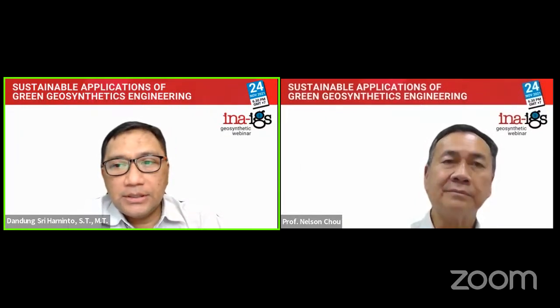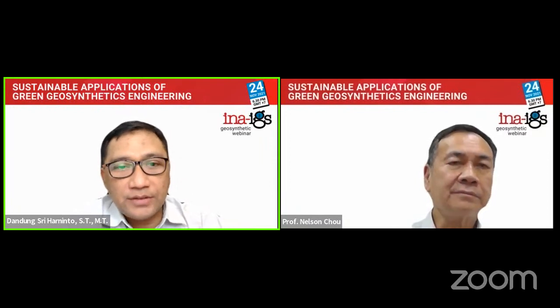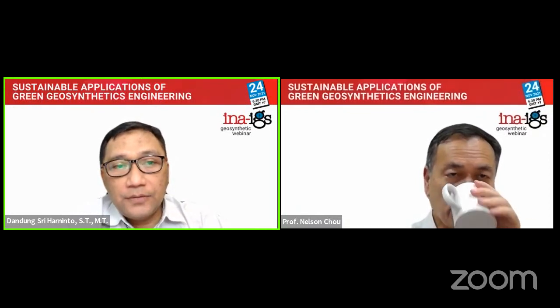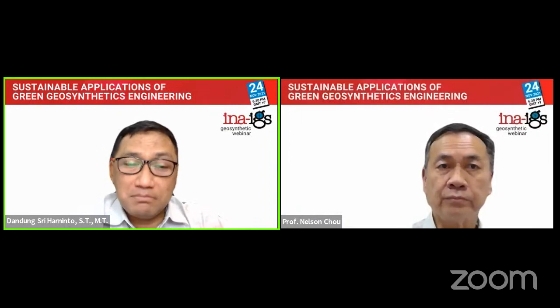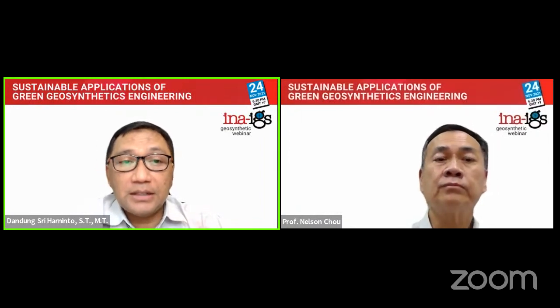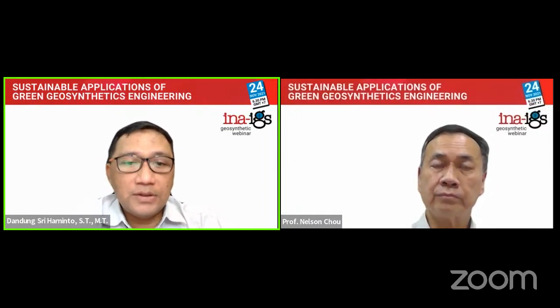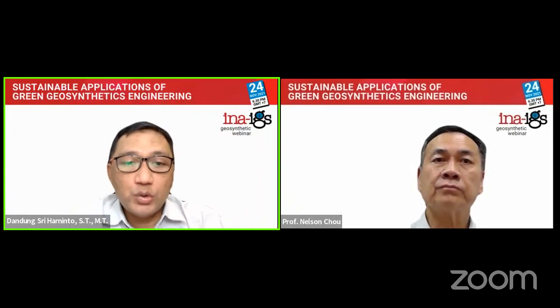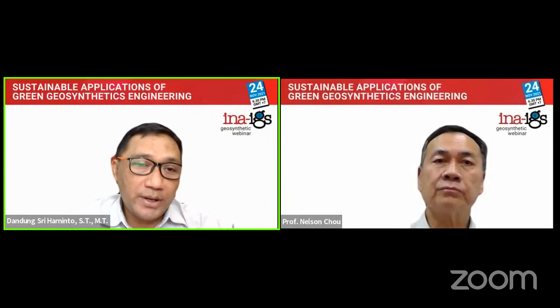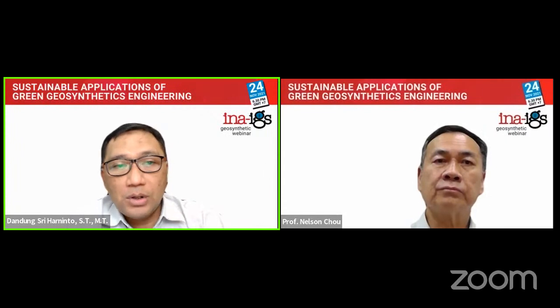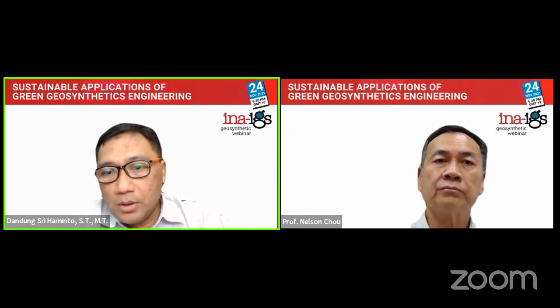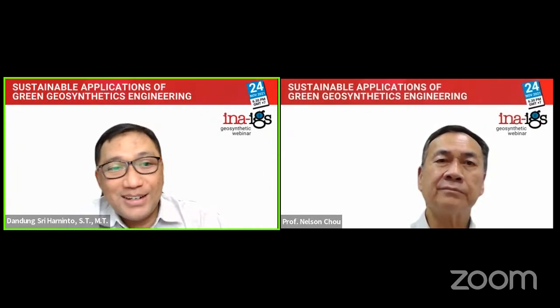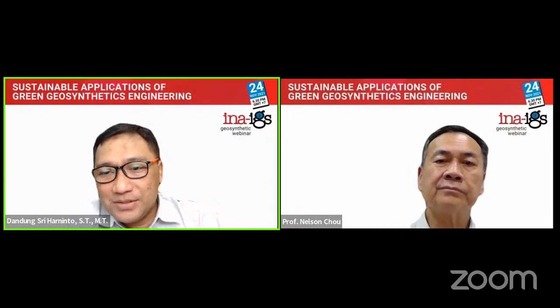Yeah, we cannot reduce settlement, but only the differential settlement. And we can also use, like, prefabricated vertical drains to accelerate not only consolidation, but also deformation during construction. So during operation, we will have no more deformation. I mean, that is additional explanation about the excessive deformation.